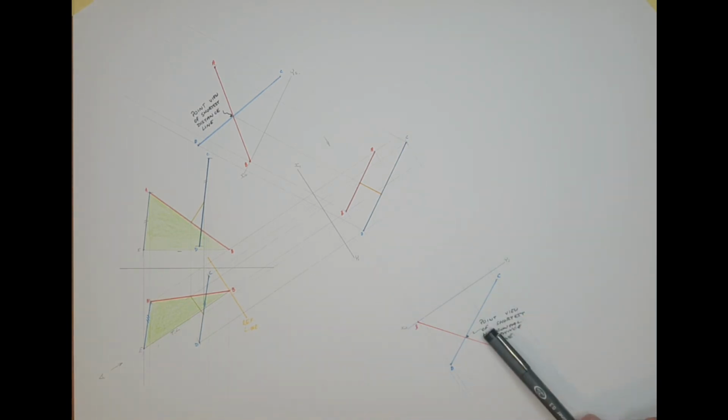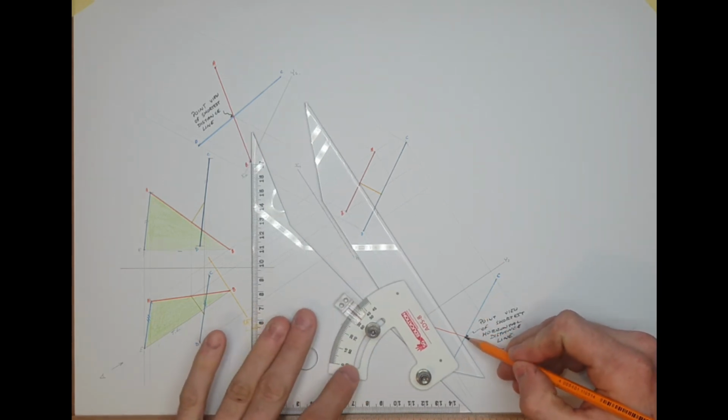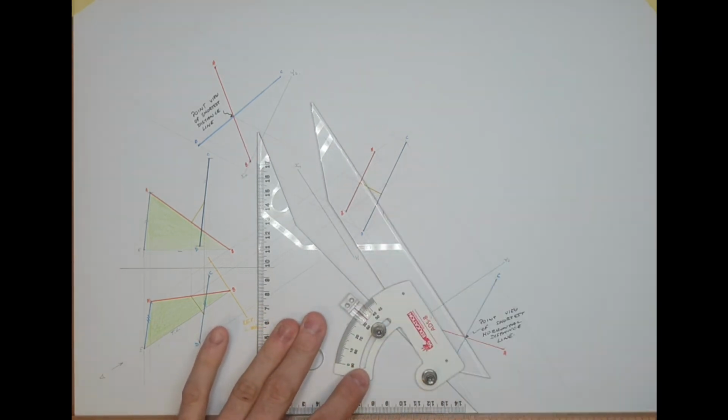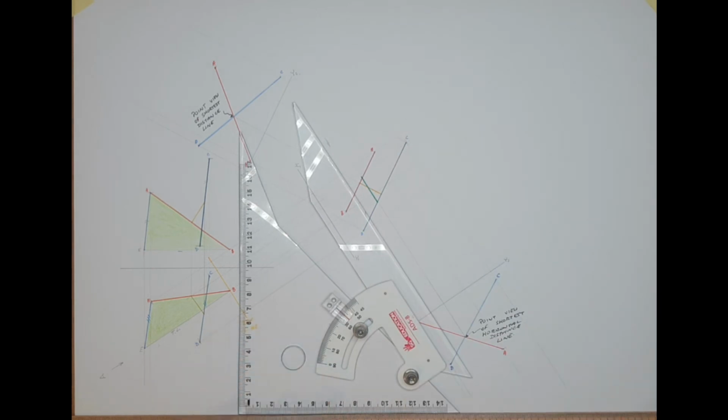If it's a point view of a line here, it's going to be a true length back here in this last view. So let's project it back. Let's take that back through, and from that point I'll take it back through the views. There we go. What colour did I use for this one? If I just recheck here on SolidWorks again, I used green for this one, so I'm going to use green again here, keep it all consistent. That right there is the shortest horizontal distance between the two lines.